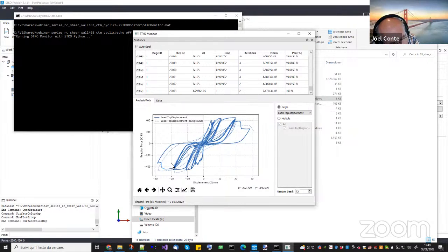Massimo, when you talk about tensorial model, sorry, Jose, you talk about the most general three-dimensional stress-strain. Any general three-dimensional model, basically, even if there are many kinds of models, plasticity-based, damage-based, at the end of the day what they do is take the stress tensor and, with a function, which is the yield surface or the damage surface, convert this tensor into an equivalent scalar.